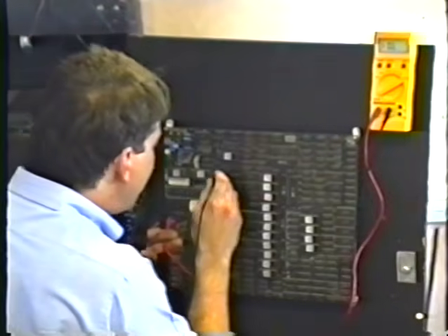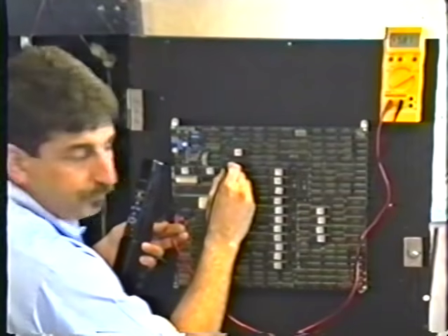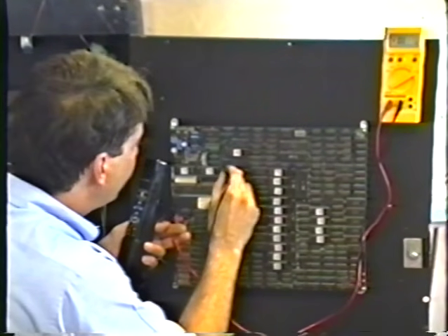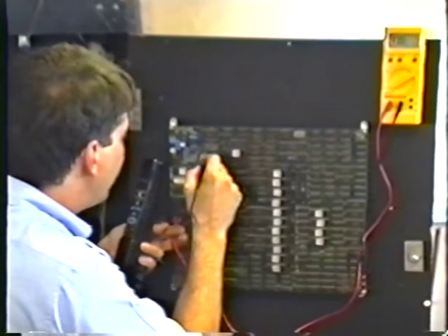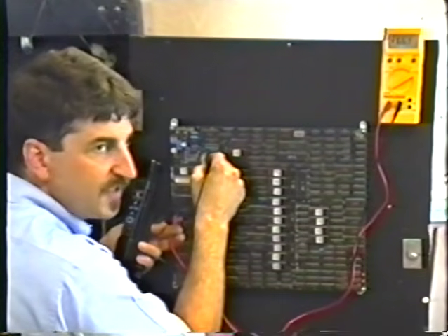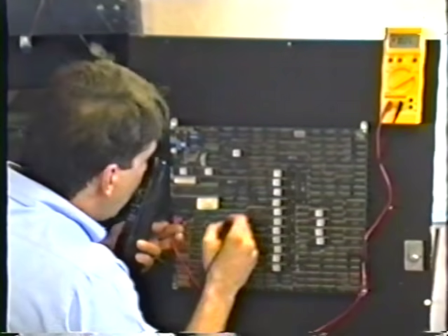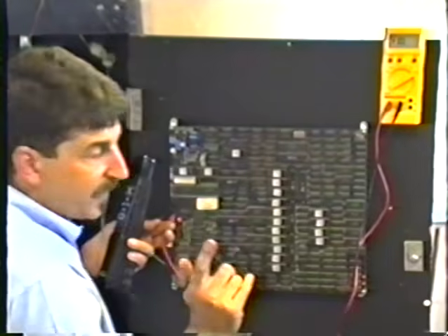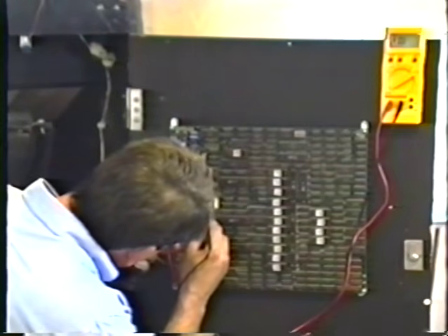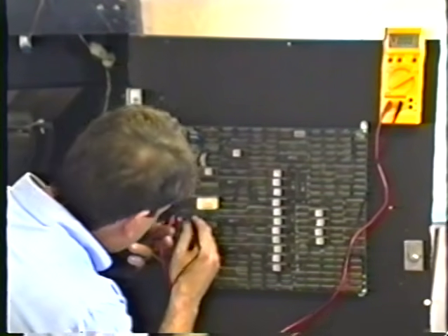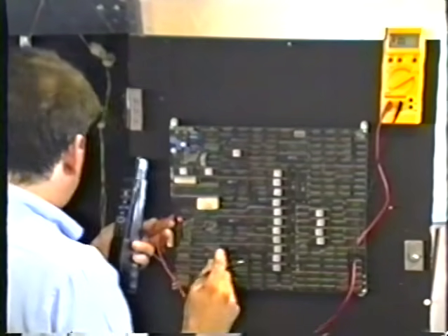When you probe the pins of the integrated circuit, you see a junction drop. Like now the meter says 0.5. No matter where I go, I'm going all over the place, and I don't even know what these pins do. 0.5. I've got no idea what these pins really do. 0.6. Do you see how they're all checking like transistors? When you get to the bad one, you're going to see something a whole lot lower. Maybe something like that. Or, well, here, let me see if I can find a better one here. That's dead short. It wouldn't be that bad. What am I doing wrong?